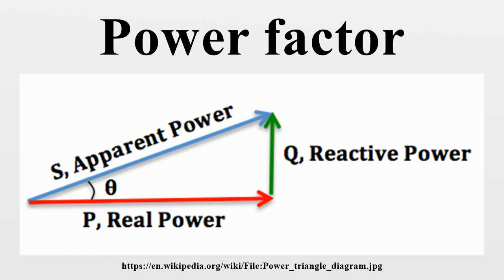The power triangle. We can relate the various components of AC power by using the power triangle. Real power extends horizontally in the i direction as it represents a purely real component of AC power. Reactive power extends in the j direction as it represents a purely imaginary component of AC power. Apparent power represents a combination of both real and reactive power, and therefore can be calculated by using the vector sum of these two components.